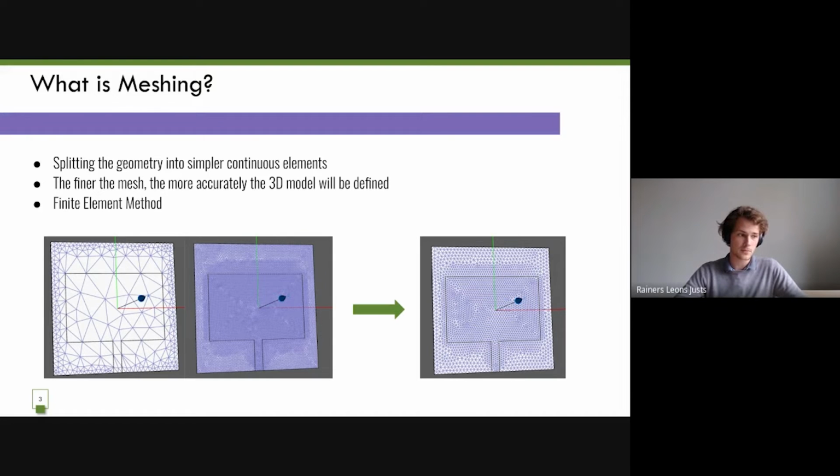The finer the mesh you have, the more accurate results you will get. However, there is a limit: you can decrease the element size of your mesh, but it will not net you more accurate results. It will give you a much larger calculation time, which grows exponentially the larger the mesh size. So mesh optimization is an essential part of simulations, as you'll see.